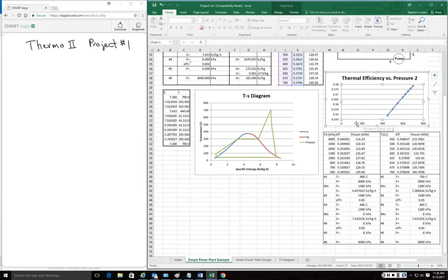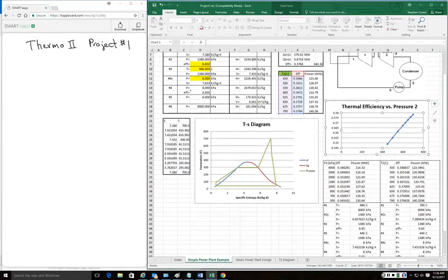And I guess I can still have it go to 0. So what I'm seeing here is that the efficiency just continues to increase as I adjust the temperature up, which probably makes sense in that I would expect it to go up the higher the temperature difference between my low temperature sink and my high temperature reservoir.